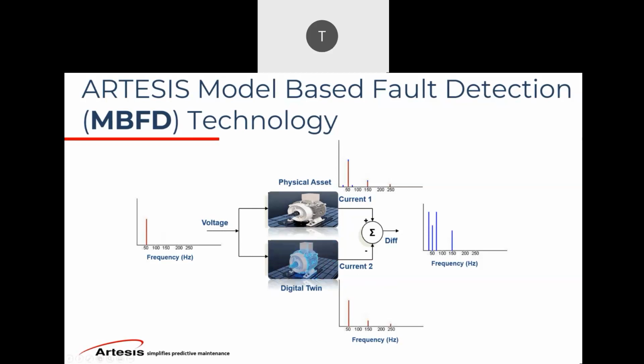So if you see here, you have some amplified harmonics, and based on the frequency of these harmonics and the magnitudes, we can easily tell what sort of mechanical problems we are seeing here. To give you an example, if you had an imbalance, you would see one-times RPM peaks plus and minus around the line frequency. If it was 60 hertz, let's say, on an 1800 RPM system, you would see a peak at 30 hertz and a peak at 90 hertz. That will tell you that this is an imbalance issue on the system. This was just one example.